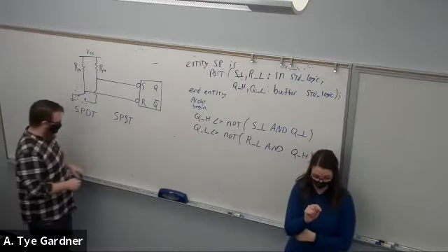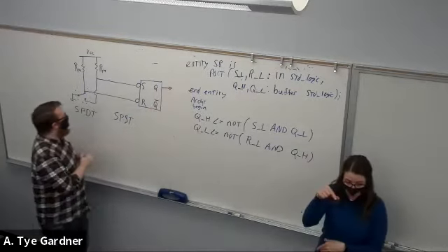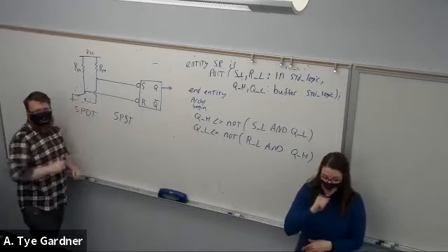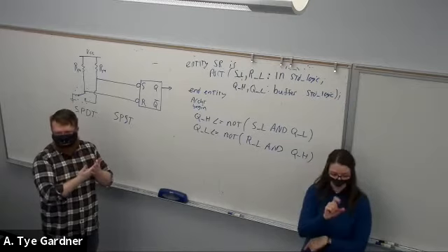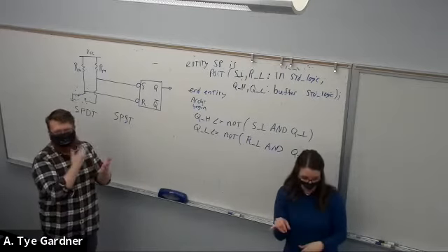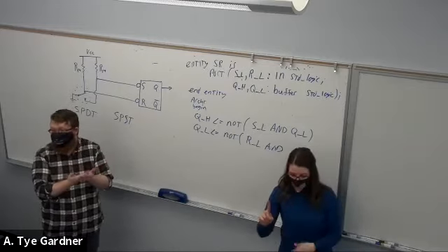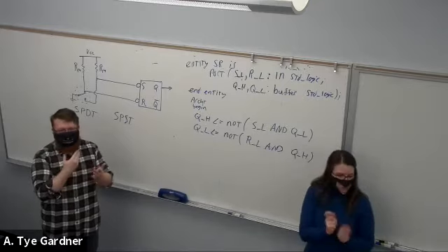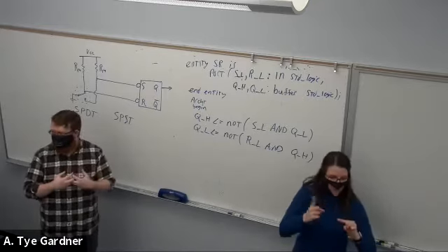What happens is if I'm counting on Q rather than counting the output of the switch, it bounces and just goes set, set, set, set, set. Which we don't care about, right? That's just going to set it to 1, set it to 1, set it to 1. Okay, not a problem. It didn't change. There was no connection, disconnection, connection, disconnection, because the set remembered what it was before.